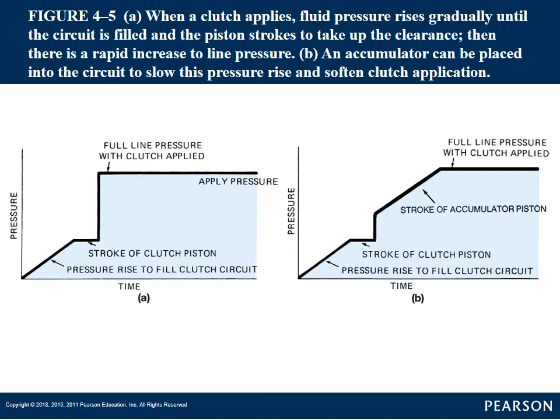Where B, you can see with an accumulator, that rise of pressure happens gradually and more at an angle before it finally fully fills up. So there's less harshness to that shift. The shift takes longer, but there's less harshness to it.